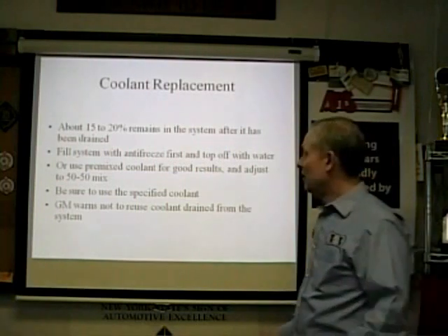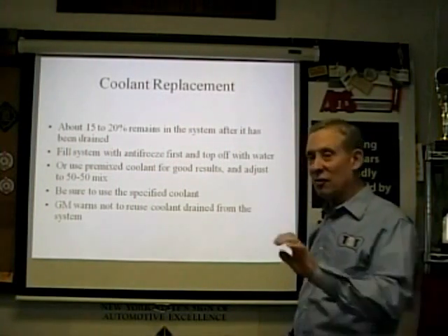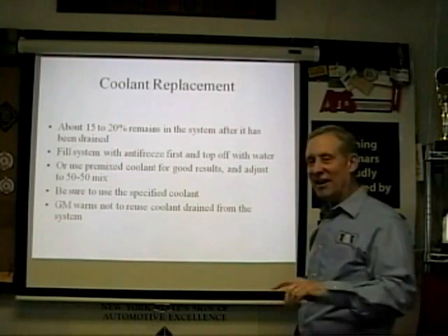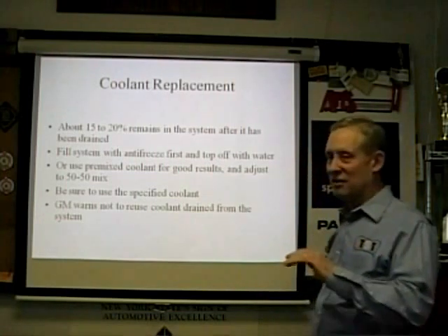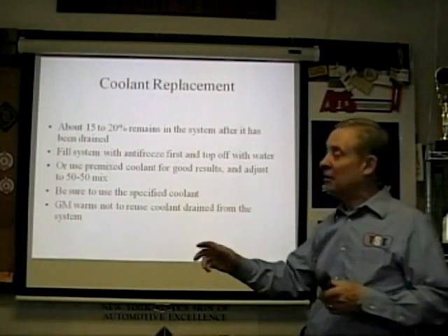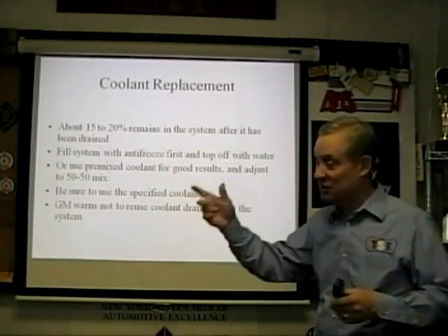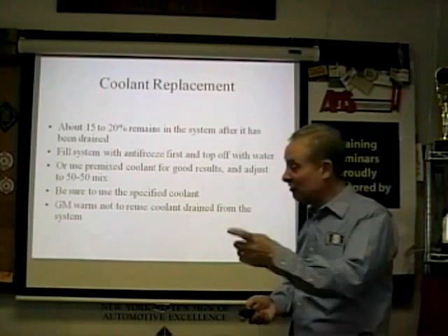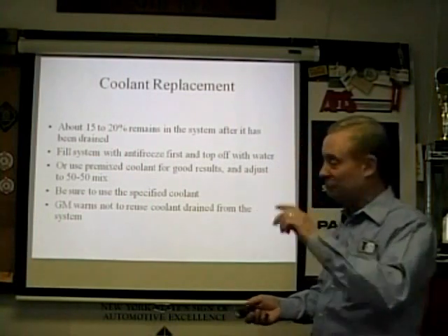Crack those bleeders and make sure you warm them up with that little electric heater nowadays. That works good. Yeah, whatever it takes. Run the air. The heating system may have an auxiliary water pump that you have to make sure the heating system's turned on, because it may not run through there without that pump running, and turn the heat up max.